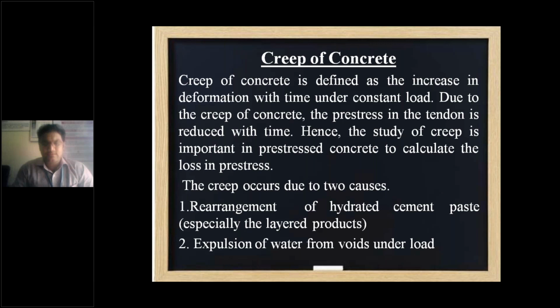Okay, the creep occurs due to two causes. Do you know when creep occurs? One is rearrangement of hydrated cement paste, especially the layered products. Layered products means when you are casting a member in an add-on portion, not as a single unit but casting individual parts and joining them, such members have less creep. So creep occurs for one reason where you cast elements individually, instead of casting a single unit, and that reduces creep. And the next one, expulsion of water from voids under load.